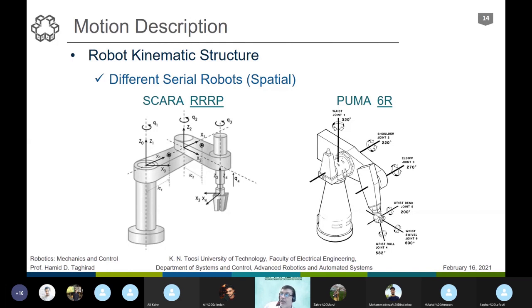But the structure they have, as you see, has a rotation here, again out of the plane. But instead of having an in-plane like this, we have 2 motions perpendicular to the gravity. And this helps us so that the weight of the robot is not providing resistance to the motion, so we can have faster motion. This structure, in terms of mechanical design, can be quite fast.